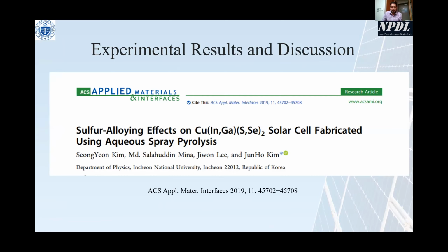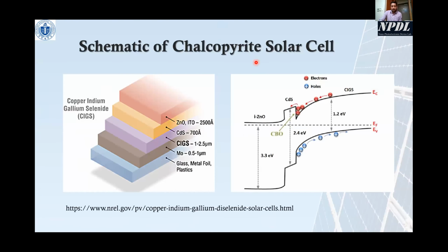Usually in our CIGS fabrication that we proposed in our experimental talk, we use a cadmium sulfide buffer layer. We know cadmium is toxic, but many other buffer layers are also proposed. The buffer layer is the n-type layer, a combination between the window layer and absorber layer, so the buffer is an intermediate layer. Now researchers want to move to a cadmium-free buffer layer because cadmium is toxic.